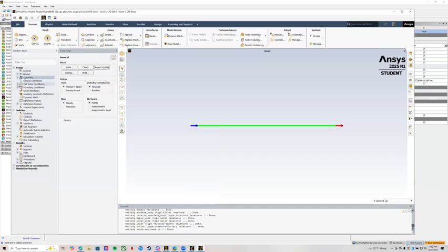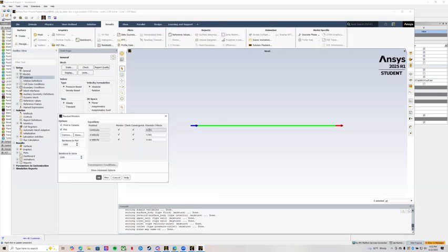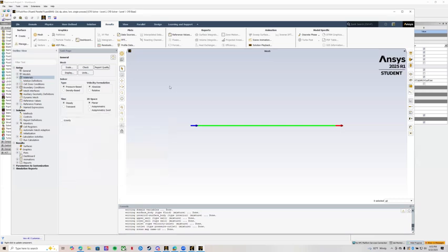Tap up here so that we can close that. Next thing you want to do is go to your results just real quick. You want to change your residuals. That is basically the numbers you're going down to. We're going to put it down to 1e-6 just so that way we can have the best amount of data we can. Just copy and paste that into each box to save some time here. So once you have that done, you can press OK. Residual is more like the range of where your data is going to.